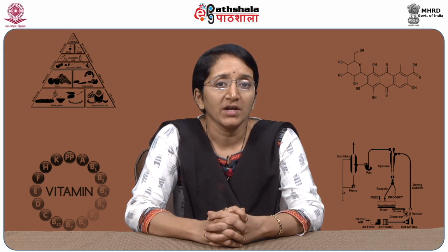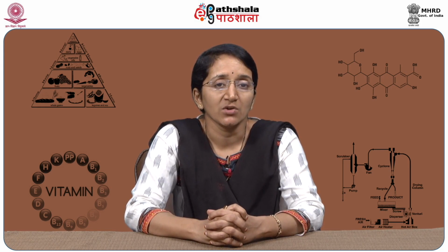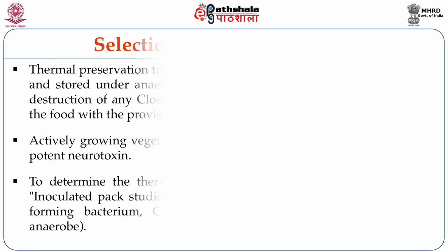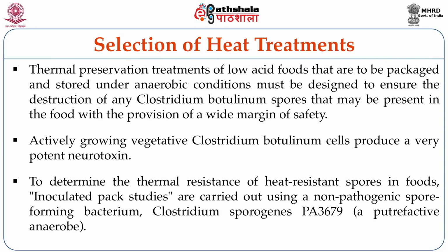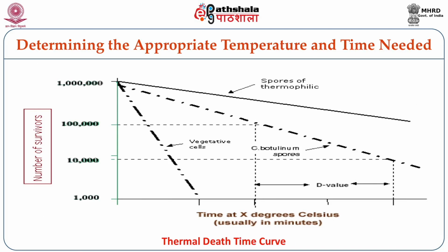Therefore, it is important to understand the destruction of Clostridium botulinum spores. To determine the thermal resistance of heat-resistant spores in the foods, we have to conduct some inoculated pack studies using a non-pathogenic spore-forming bacterium. Now let us try to determine the appropriate temperature and time needed to make sure that heat-resistant spores like Clostridium botulinum are also destroyed during the heat processing.